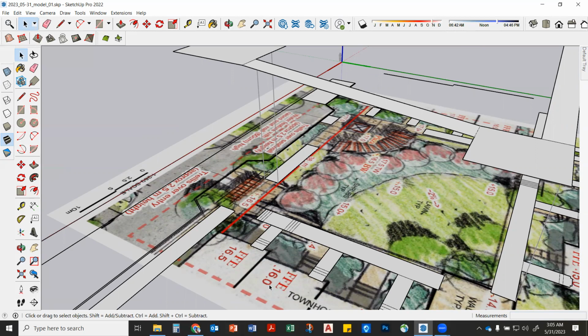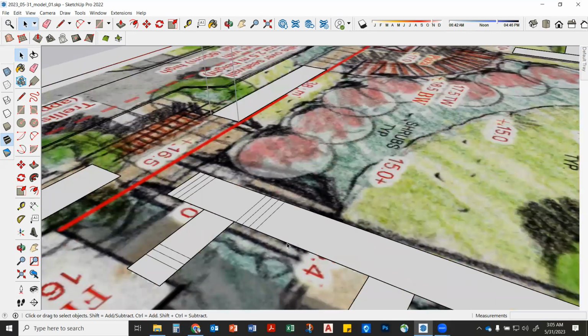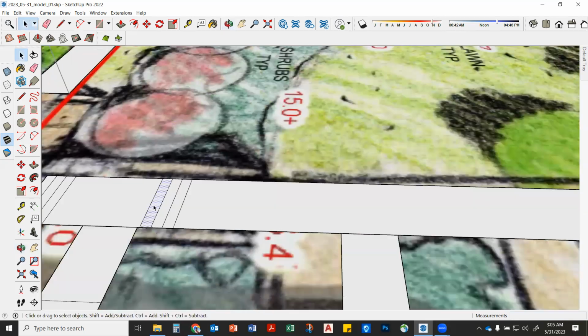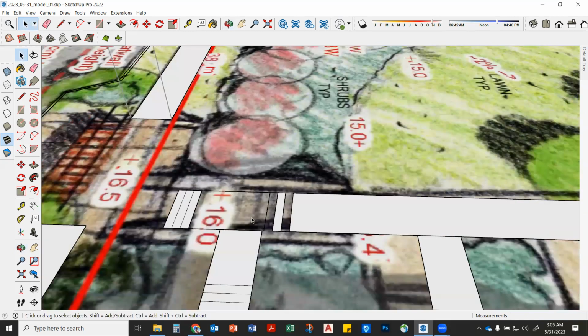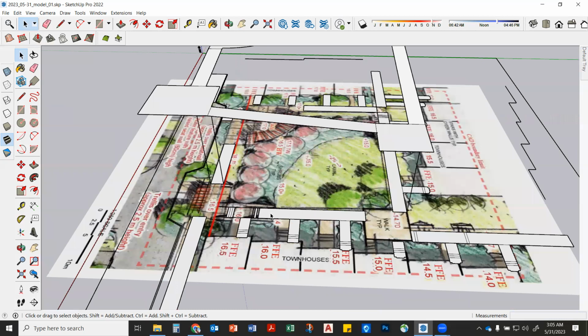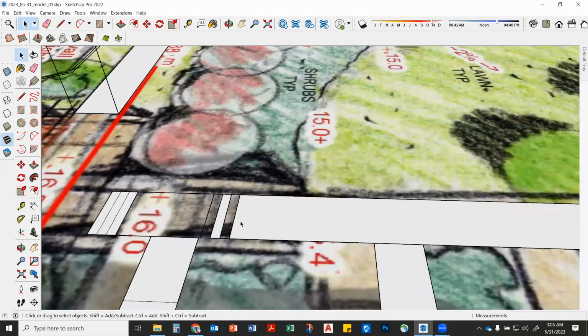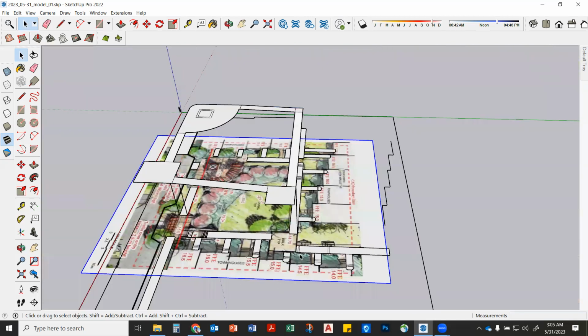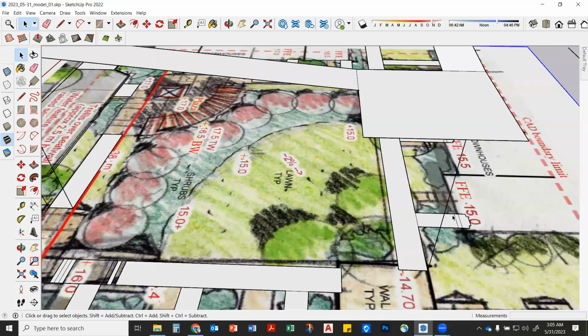Yeah. Good. Does everybody's line work look like this? Yeah. If not, if you have some holes in it, right? If there's not faces in a couple of these, you can come in and all you have to do, how do we make faces? You can use the make faces command if you want, right? But the old school easy way, so we've got to make sure we're getting into the file. If your image keeps getting selected, right? You see this? Keeps getting selected. You can actually just select it once.